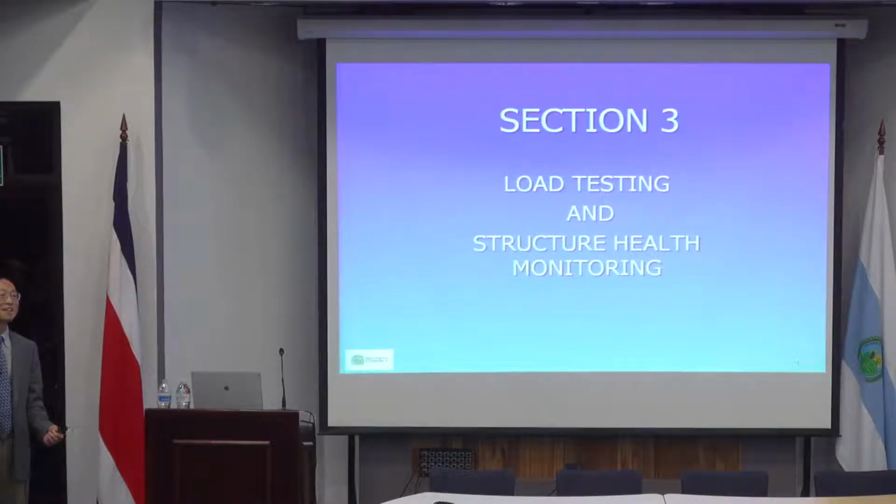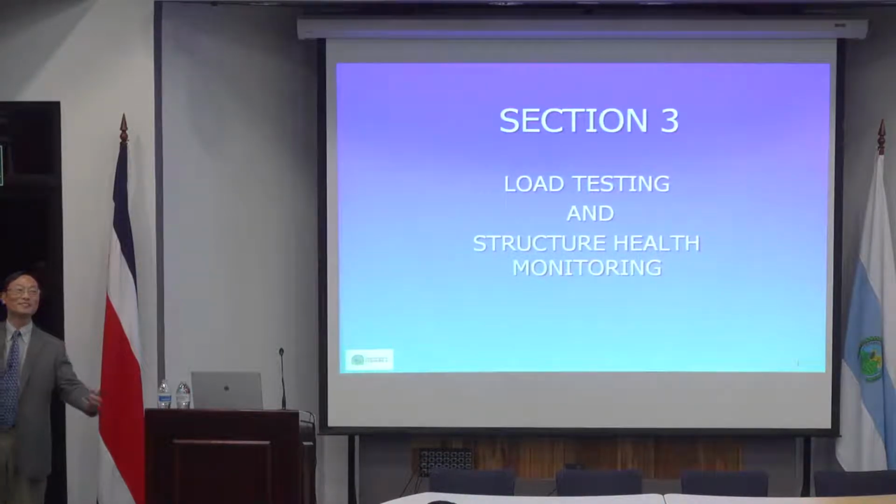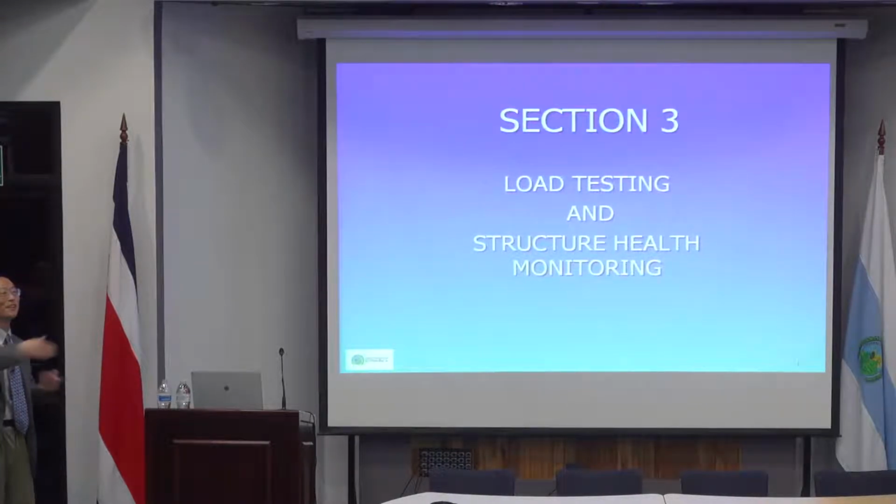Again, just like a deck, for example, if we have a very, very weak deck, like a timber deck, when the truck comes here, because timber is so weak, the other girders will have no impact. Just one girder deflects a lot more than the others. When you have a very, very strong deck, like a very thick concrete deck, because the deck is so strong, it will force all the girders to deform uniformly. That gives you much, much better distribution.